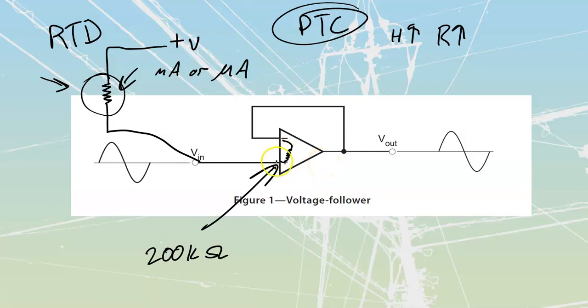Once again, not going to be important for us other than to look at this thing as a 200,000 ohm resistance, and that this over here is going to be a very small value of resistance. It could be anywhere from, let's say, 10 to 500 ohms that we are going to have through there. We are going to have the bulk of our voltage dropped across here, but as the heat around it changes, we are going to change our resistance. So if we increase heat,